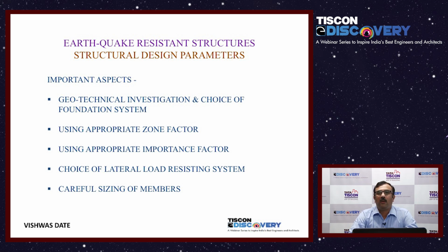All of us tend to first arrive at a system which will give us proper gravitational load flow. Not always do we think of how it will also prevail laterally, and that is where the choice of lateral load system comes into play. As we saw, we have to make judicious calls. We have to choose which columns, which walls are the most logically placed elements which will help me support my earthquake. And those things you make stronger.